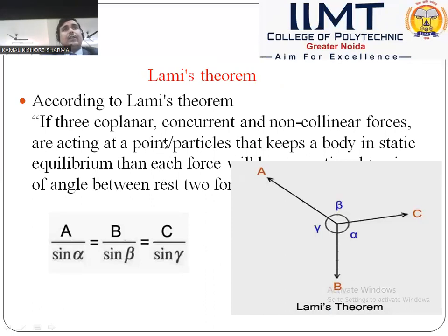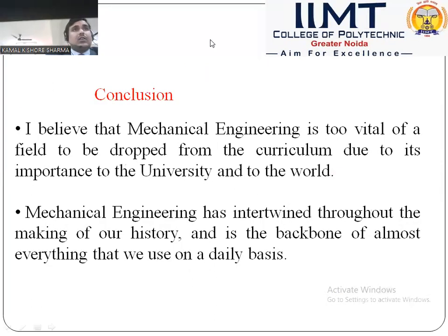So one of them is Lami's theorem. Here, if three forces, coplanar, concurrent and collinear, are acting at a point or a particle that keeps the body in static equilibrium, then each force will be proportional to the sine of the angle between the other two forces. So here Lami's theorem: if three concurrent coplanar forces acting at a point are in equilibrium, then each force is proportional to the sine of the angle between the other two forces.